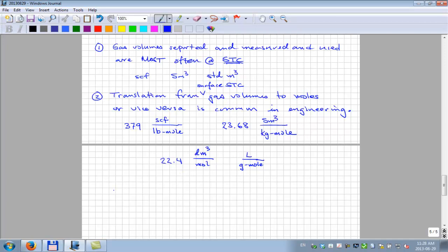And I'm going to give you numbers. This is 10.73146, and that's using pressure unit of PSIA, temperature unit of Rankine, volume in cubic feet, and mass unit of pound. So it'll be pound moles. And the universal gas constant for, what's the SI universal gas constant?